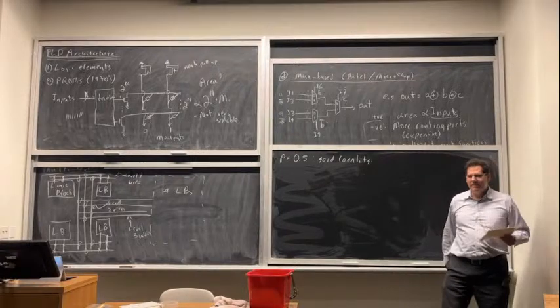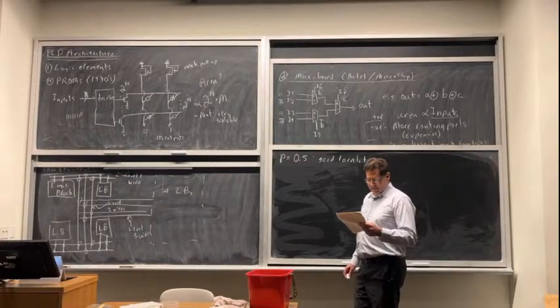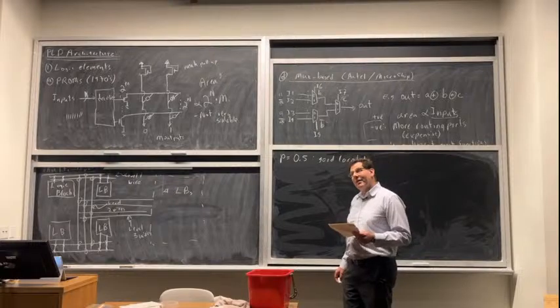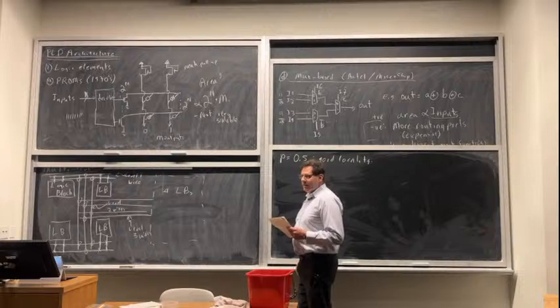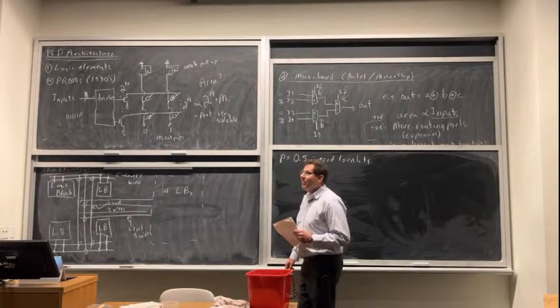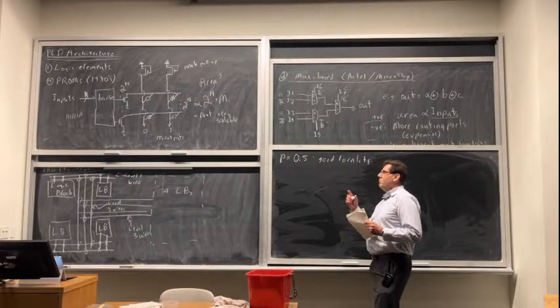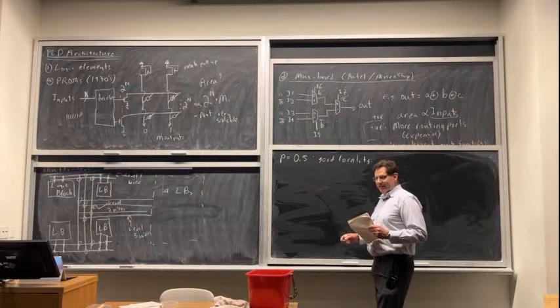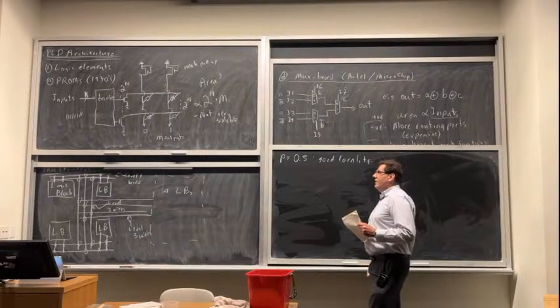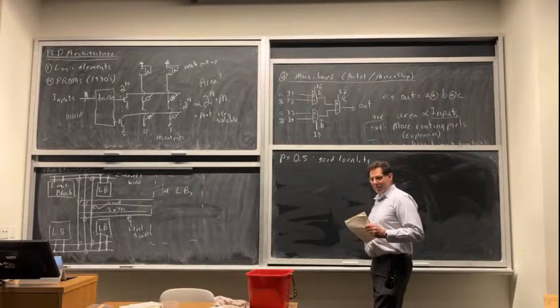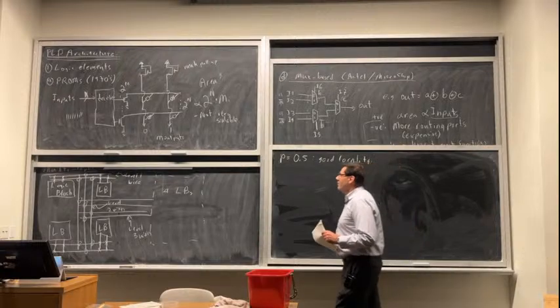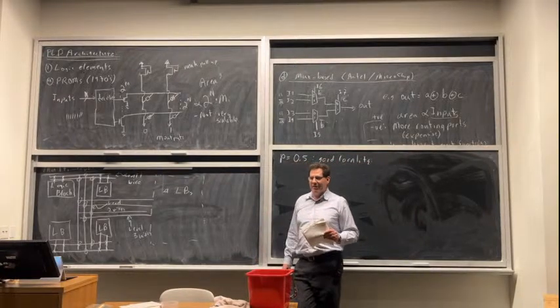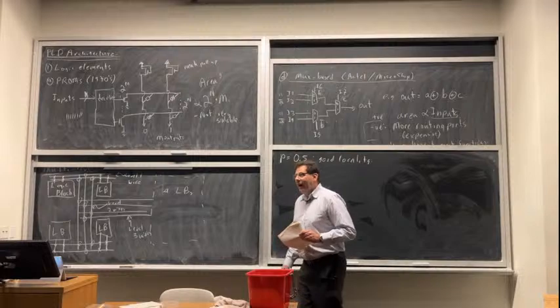Yeah, what do you think? I have a guess, but a MUX architecture. I haven't thought about that one. So how are you thinking of that? It's logarithmic, right? As I put more muxing in, the increase in the gates is logarithmic in the input, and 0.5 is square root. Oh, so you're thinking of a lookup table. Is that what you're saying? Like, you're thinking MUX architecture kind of like the lookup table, where the number of inputs to the lookup table will grow logarithmically with the size of what's in it.